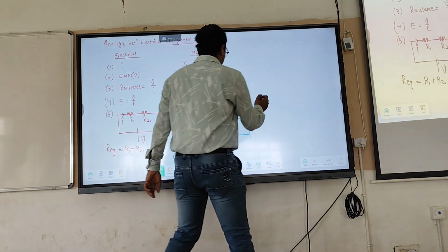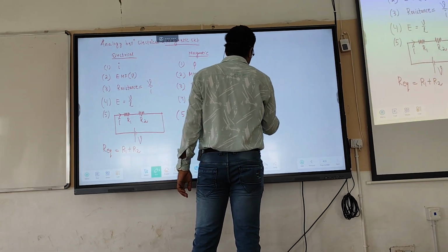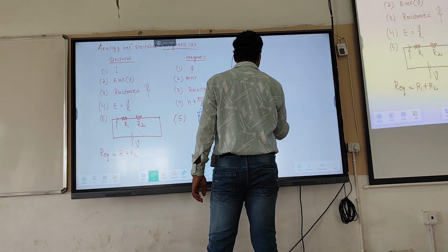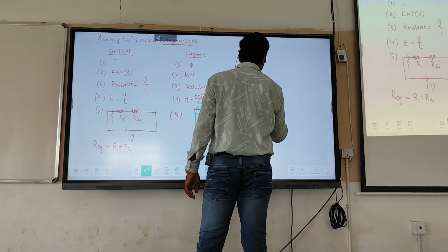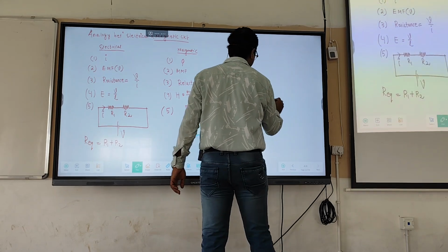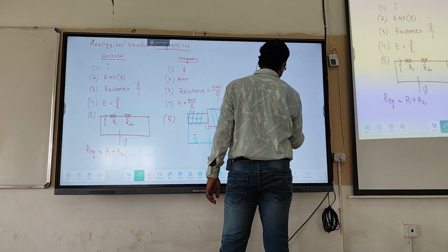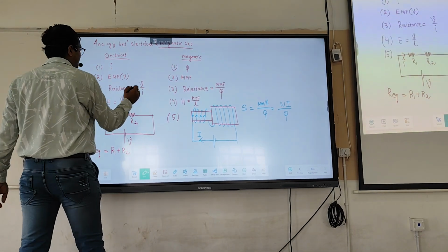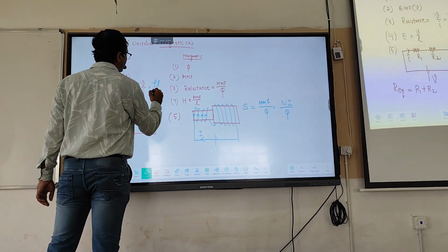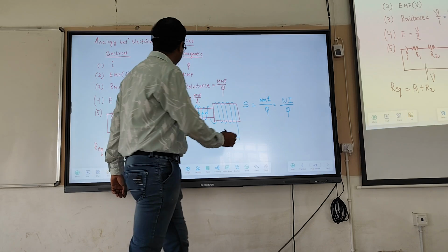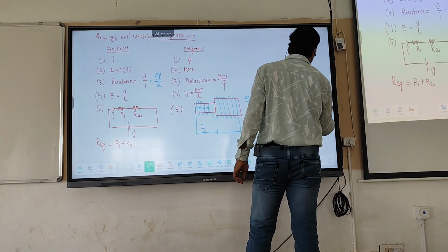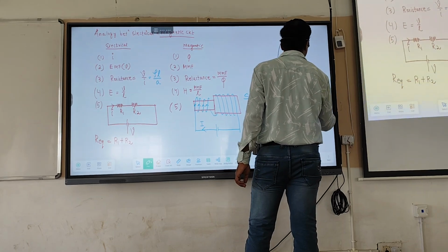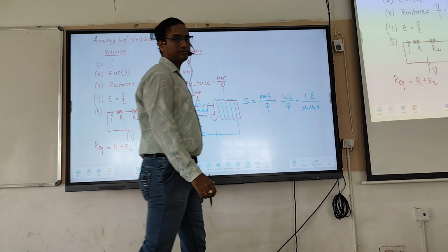Here, what is reluctance? Reluctance is equal to MMF divided by flux. What is MMF? NI. Divided by flux. We know that resistance is equal to rho L by A. Reluctance is equal to 1 by mu naught mu r, times L by A. This is the formula for reluctance.